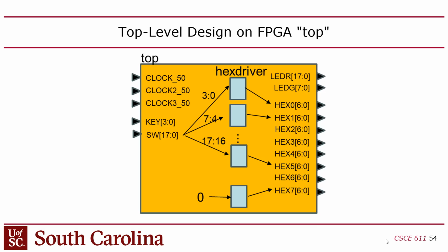They're called hex drivers. Charles came up with that name. I don't care what you call them. They go to something that does the 4-bit to 7-bit decoding. And then you're going to connect the outputs of those to the hex outputs. As I mentioned, there's 56 total bits coming out, 8 digits, 7 bits each. Okay? And they're all enumerated through their name. Okay? So that's the top.